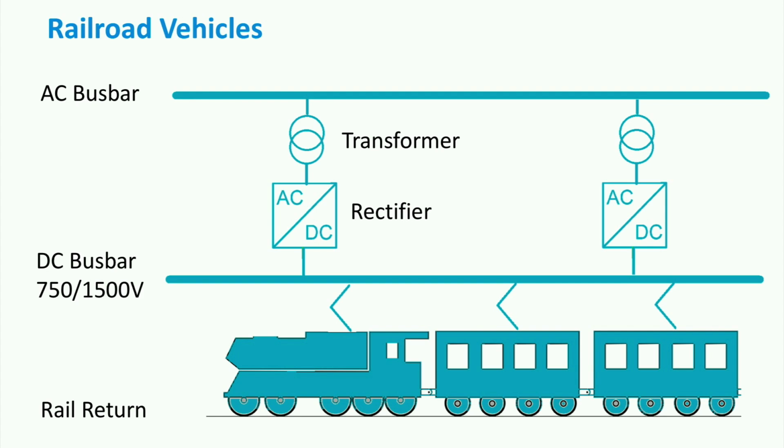Monopolar DC is preferred in this architecture as it simplifies the catenary system. A rail return is used, which is the method usually adopted to reduce costs. But it does present some disadvantages, such as damage to metallic structures and interference with signal circuits.